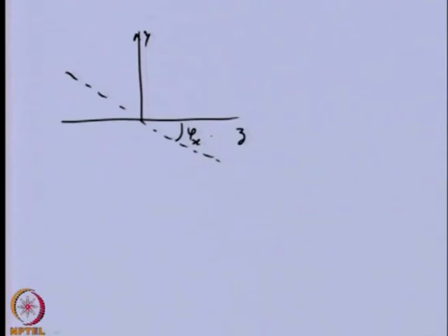Because of this tilt we have this much deformation of the shaft, which is phi x times L by 2 if the total length of the shaft is L, and the same on this side also. You can see that here the spring is getting compressed, so the force will be upward. Here it is getting extended, so this will be downward, and the values of these forces will be